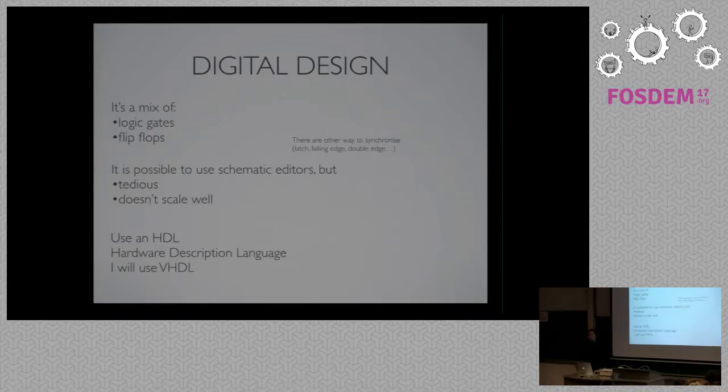Computation, synchronization. It's possible to design a real circuit using a schematic editor. It works well for very simple circuits, but as soon as it becomes a little bit complex, people prefer to use an HDL, which is a hardware description language. It's like a language, C or Java, but one that targets hardware specifically. There are two main hardware languages, Verilog and VHDL, and here we use VHDL.